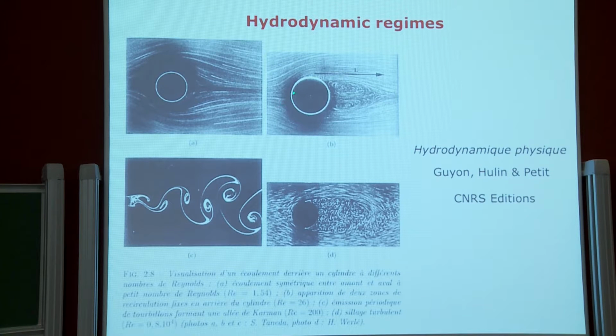Increasing the Reynolds number, you start forming different patterns at the rear parts of the flow. So behind your object, you see these circulations of your fluid. And then if you increase further the Reynolds number, you will start generating this type of regular structure, so that it's not static. In fact, they move, and you emit this type of vortices in a regular fashion. And if you go to extremely high Reynolds number, then it becomes chaotic. So you see that depending on the Reynolds number, you will have different contributions to momentum transport and mass transport.